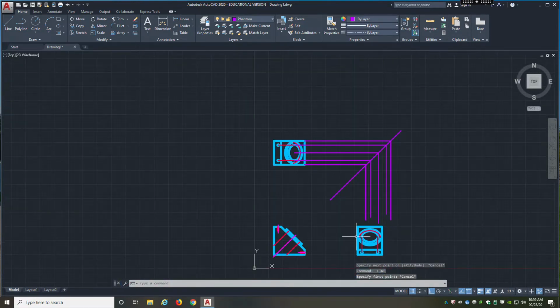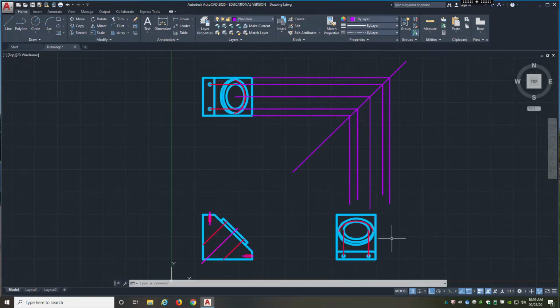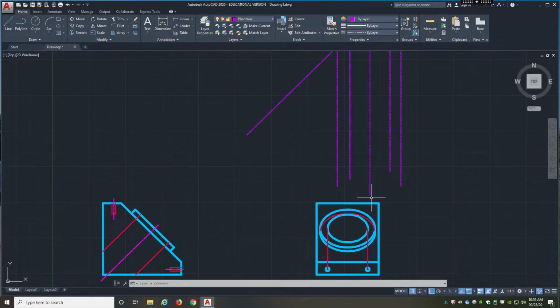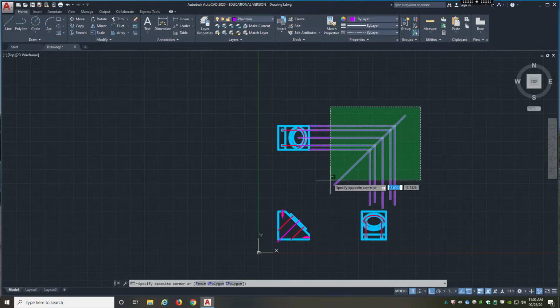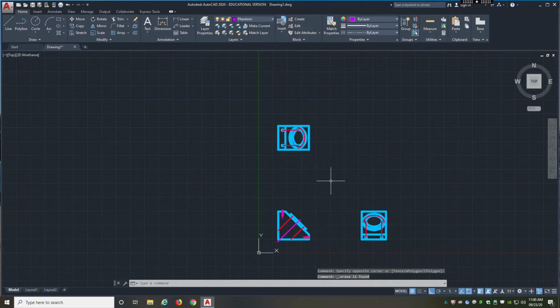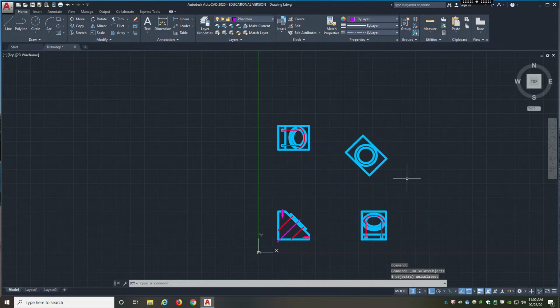And again, we're pretending that this view didn't exist yet. So what I would do is use miter lines, and then I would drop my extensions, and also use the extensions from my front view to create the view. So I was off by maybe an inch or two, just kind of doing it on my own. But that's essentially what you need to do for miter lines. I'm going to delete these, and I'm going to right click, go to isolate, and end object isolation, bring back that view.